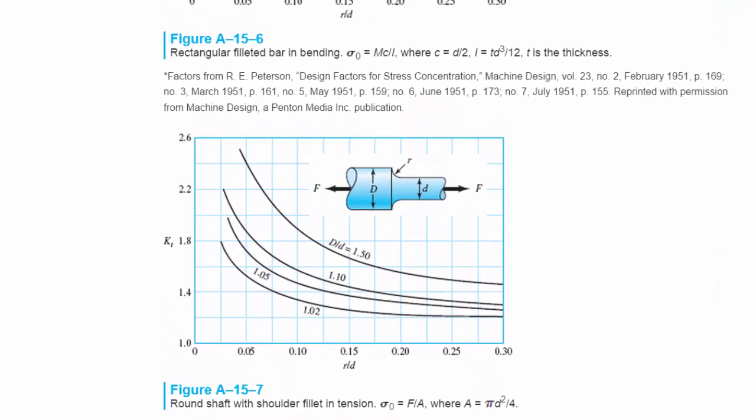We'll look at a lot of shafts in this case, and they're all basically the same. We need to have some nominal stress, so every KT is multiplied times some nominal stress. In this way, the force acting over the area is the nominal stress that this KT is applied to. So you can't apply the KT to any abstract formulation of stress, it must be according to the graph itself, where this area equals that. Based on the little diameter to the big diameter and the radius of the fillet, we can come up with what our KT value should be.